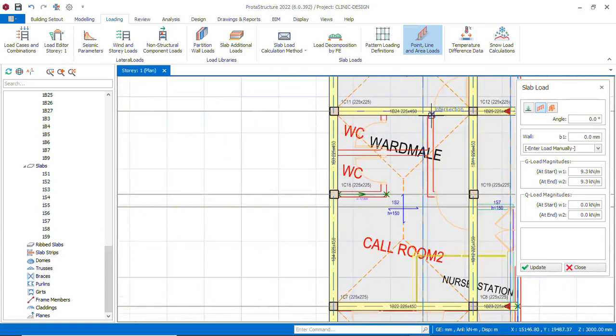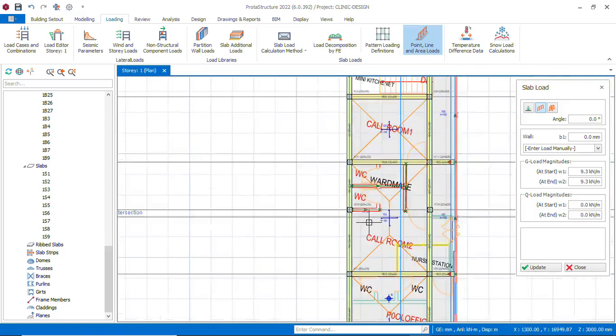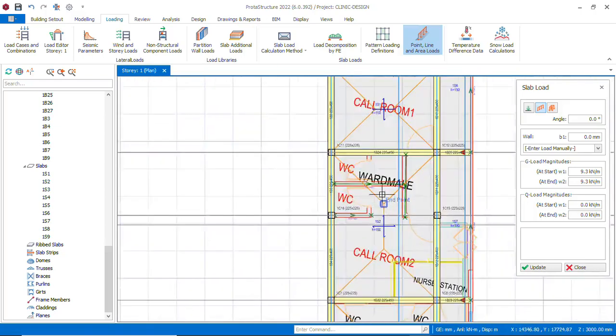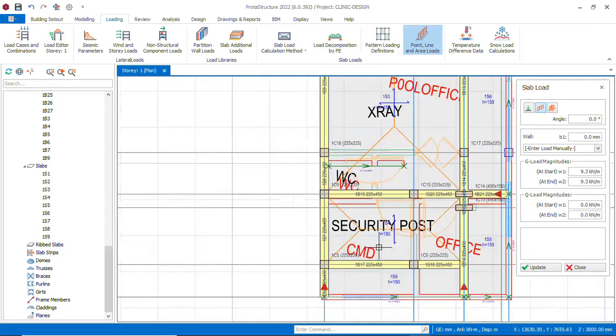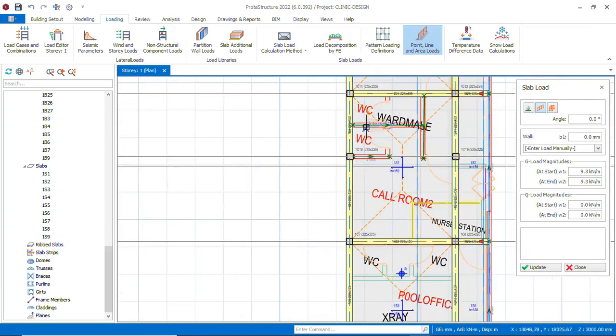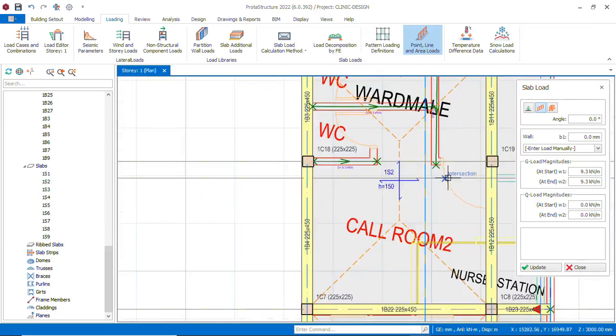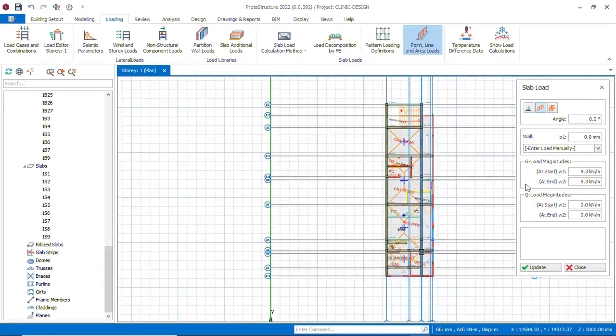I have the load here. Okay. I have the wall load here. Yeah. So this is how you assign your wall load on a slab. There is a partition wall that is starting on the slab here, so you must define it. Software will know. So let's go to 3D to see what it looks.